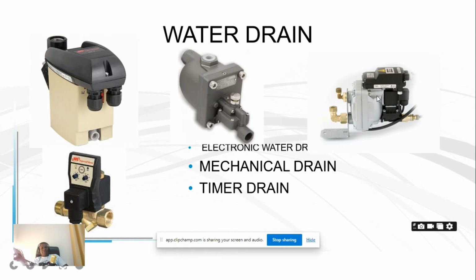Sometimes it is 115, sometimes 24 volts, sometimes 220, 230 volts, depending on the design and on what the electrical supplier will provide. And this is basically like a timer. It is set to purge at a particular time interval, maybe every 10 seconds, every 30 seconds, every 1 minute, every 2 minutes. Mostly 1 minute, 2 minutes to purge.